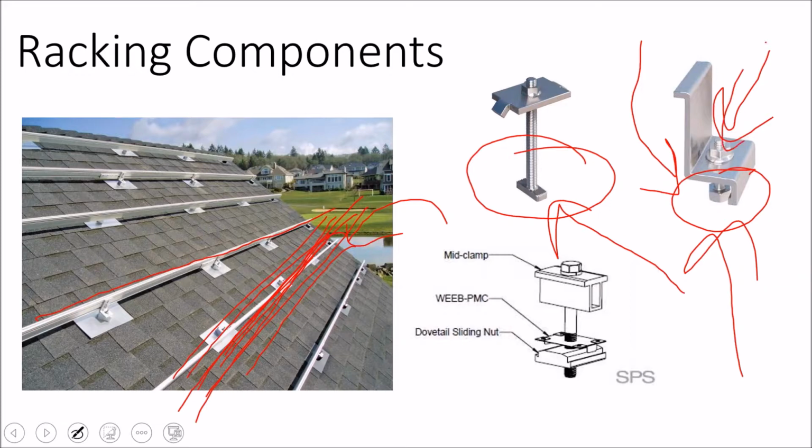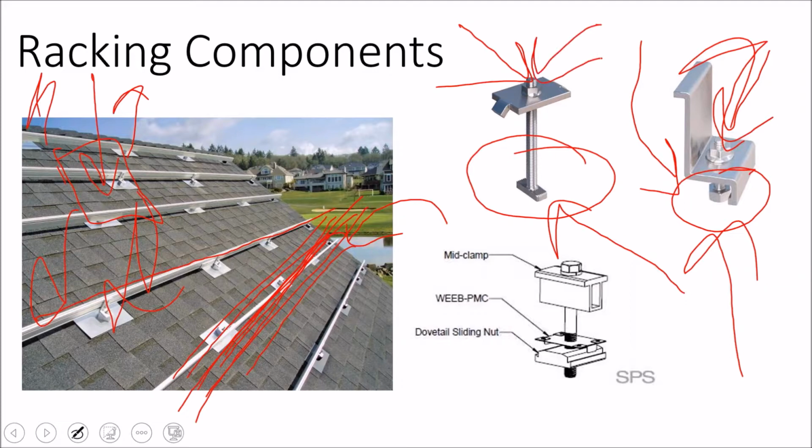And so then you go and you remove the bolt and clip and try and reset it. Well, what strips is that threading on top of the bolt. And so if you're trying to service a module that's in the interior of the array, you can just take the clips off and pull that module up and get to the microinverter that's underneath it. But the danger is you may strip the bolt in the process.